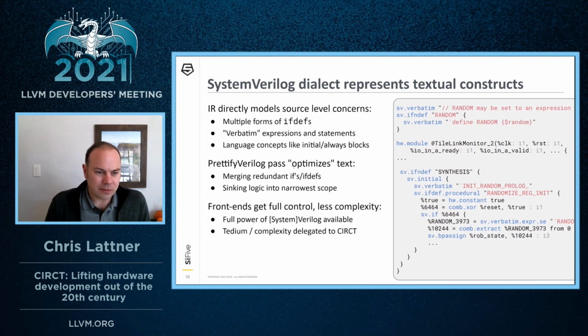One of the nice things about this is that by exposing and defining these things in the IR, what you can represent, you can transform. And so we can do syntax optimizations as compiler passes. And we can say, hey, if you have two if statements, behavioral if statements on the same condition, or you have an always block on the same clock, we can actually merge those together into one unit, which then allows recursive simplification and transformation of the IR, just like you do with a normal compiler. But now it's applying directly to source code, which has worked out really well. Next.